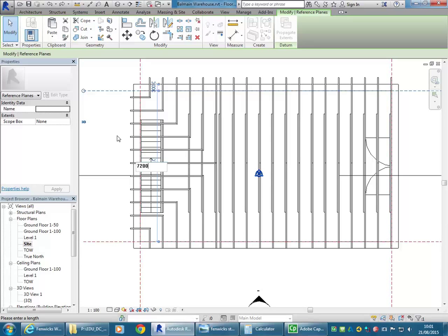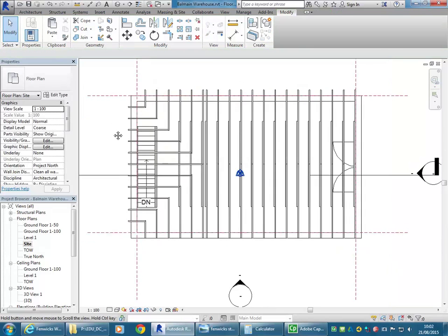Well, I'm changing the reference plane first, and then I'm going to move the wall to follow it, because it's good to have the reference planes just to establish that dimension. We're going to make it 7200, which is the way we did it last time, and that's why the roof I've done is that size. So I think we can keep it the original size. Oh no, we've got to move the walls after that.